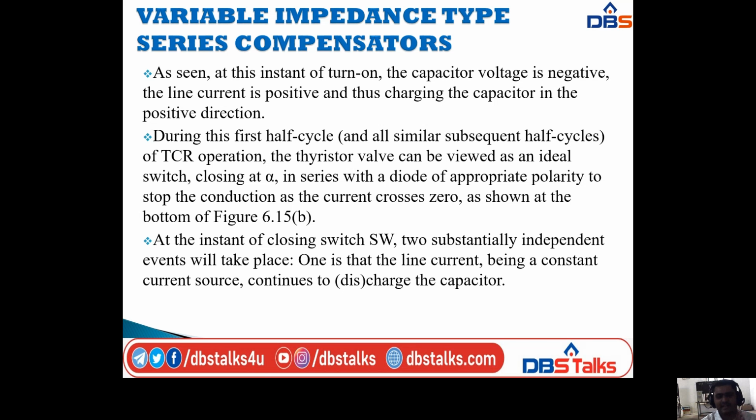During the first half cycle of TCR operation, the thyristor valve can be viewed as an ideal switch closing at alpha, in series with a diode of appropriate polarity to stop the conduction as the current crosses zero. That is shown at the bottom of figure 6.15, the B diagram. At the instant of closing the switch, two substantially independent events will take place.